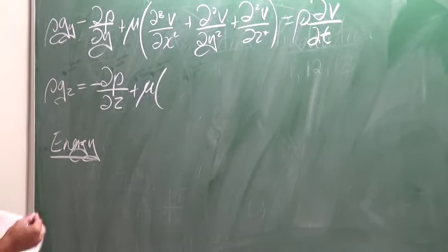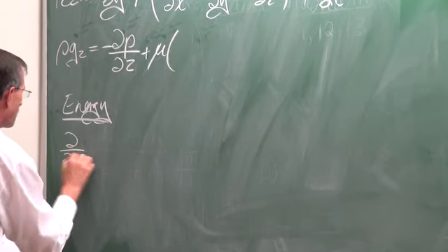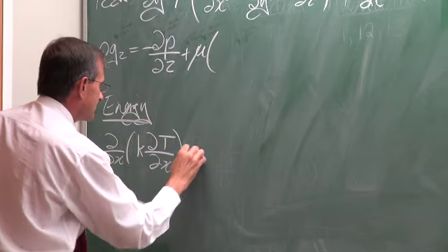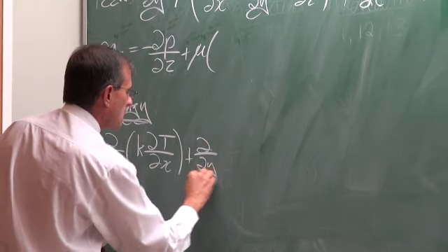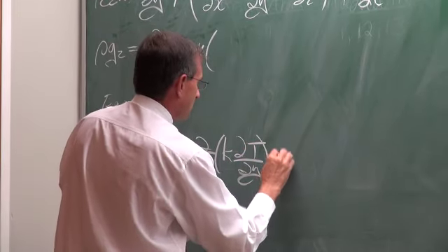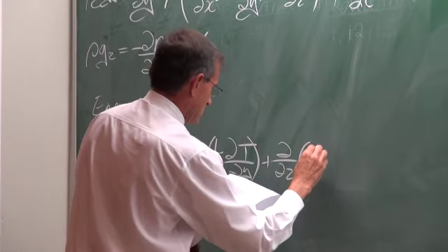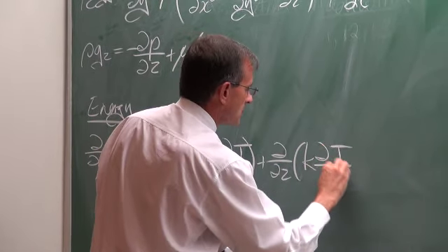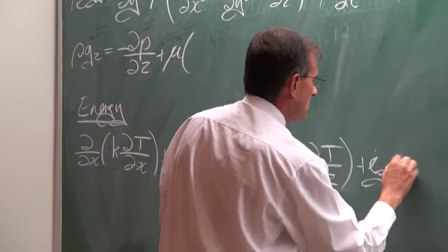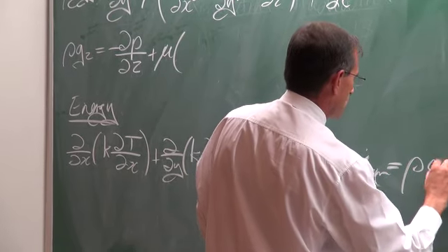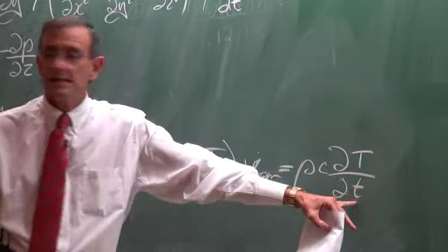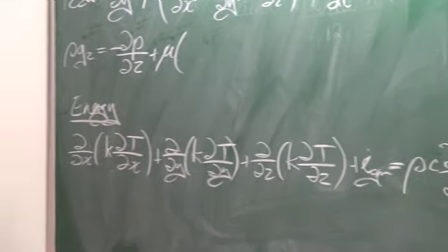So the energy equation, again, in all the assumptions, we make the very important assumption, again, it's for Newtonian flow, then the energy equation reduces to partial d dx of k partial dt dx plus partial d dy multiplied by k dt dy plus d dz of k dt dz plus E gen is equal to rho multiplied by c partial dt dt, and again where this t is now time. So that is the energy equation.